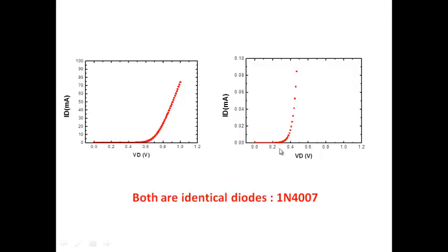There is no cut-in voltage inside a diode. There's no unique voltage. There's nothing unique about a cut-in voltage above which the current increases exponentially, very sharply, and below which it doesn't increase sharply. There's nothing like that. It all depends on the current range of interest. If you are interested in a current range of 0 to 100, well, fine, you may approximate it by 0.6. If there is some other current range of interest, you'll approximate it by something else.